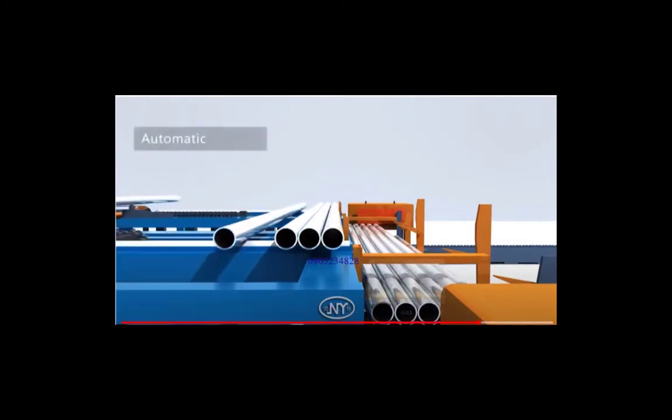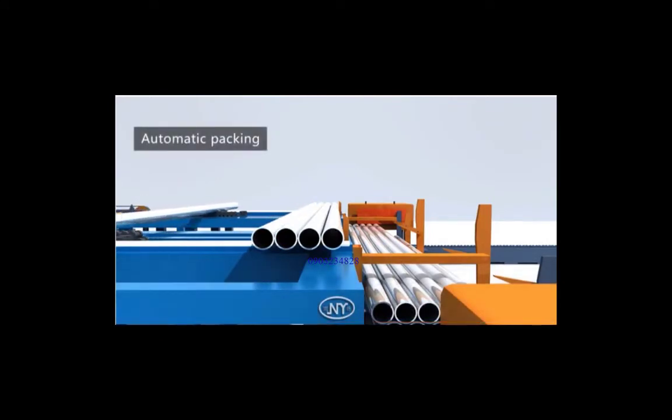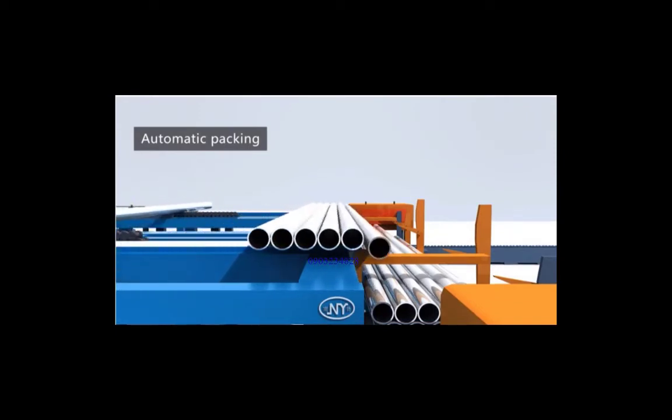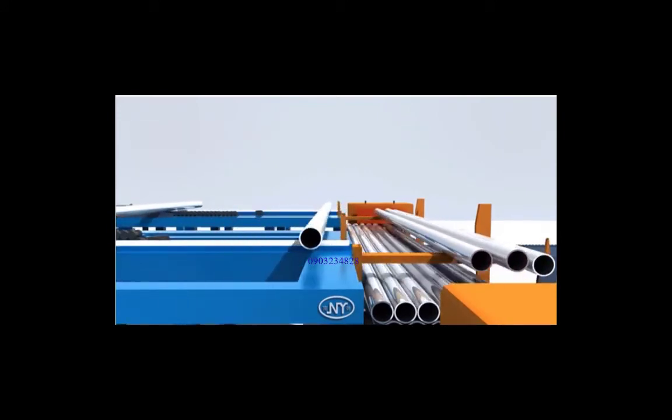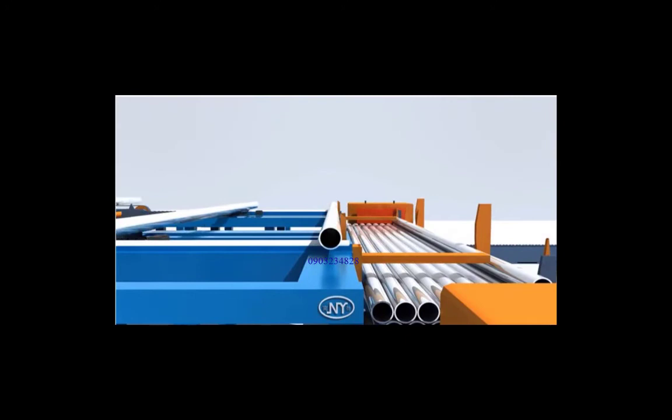The auto packing machine transfers the positive tube by power chain, then counts and analyzes to put a certain quantity of tube into the material frame layer by layer. After that, the cylinder moves to put the tubes together for humans to bind and tighten. The chain convey device moves the whole bulk of tube out of the material frame. The crane will finally transfer it to the area for finished pipe.